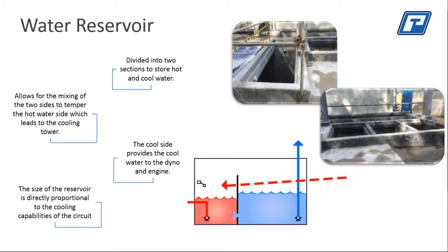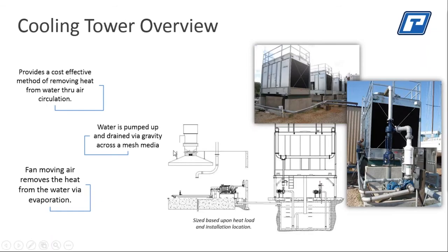That's just an average that we typically use for sizing. It works out very well. So if you've got 1,000 GPM of flow rate, approximately 4,000 liters per minute, you are going to have a 5,000 gallon or 20,000 liter total size reservoir in your system. Thanks for the question.